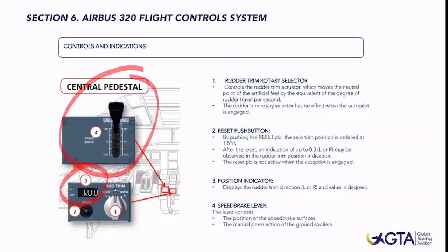If this indication is beyond this limit, I mean beyond 1 right or 2.3 left, once after landing we should call for maintenance engineers just to make a rudder inspection. How is this flight control surface? You will find this data in the Airbus manual, the FCOM, system flight control rudder trimming function.